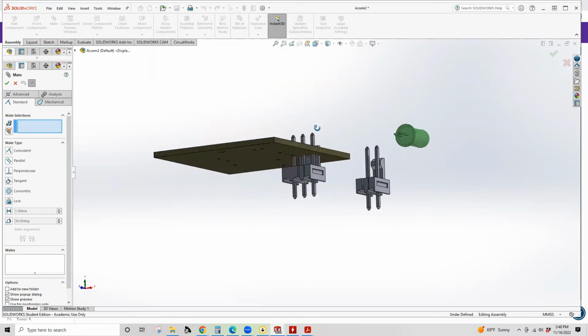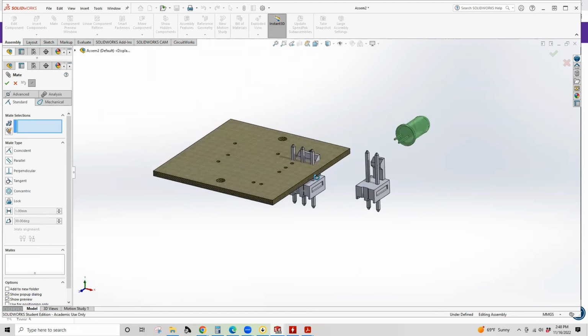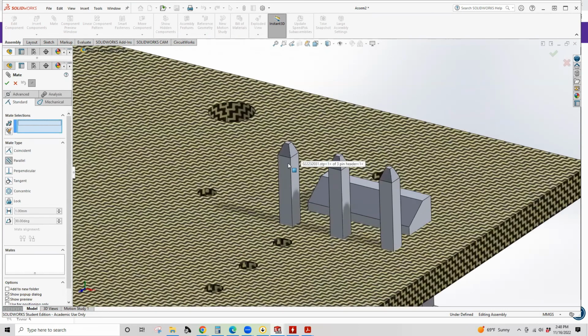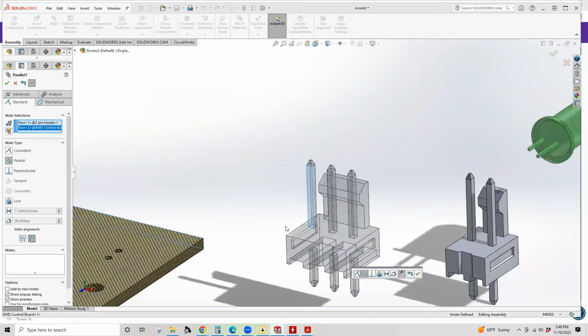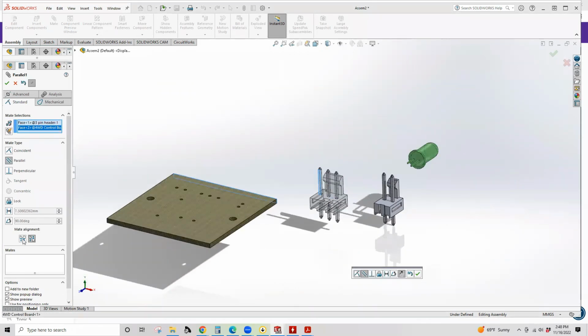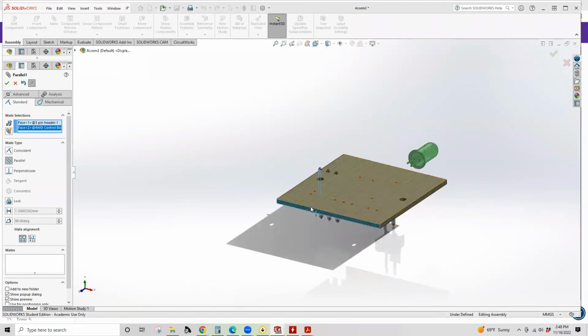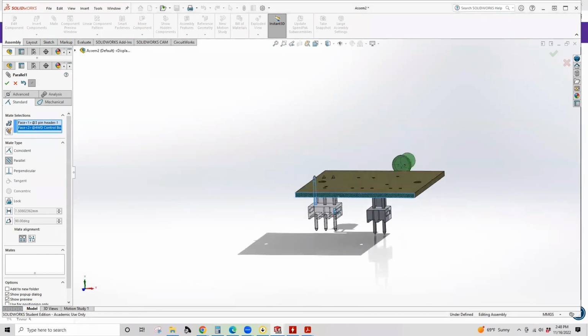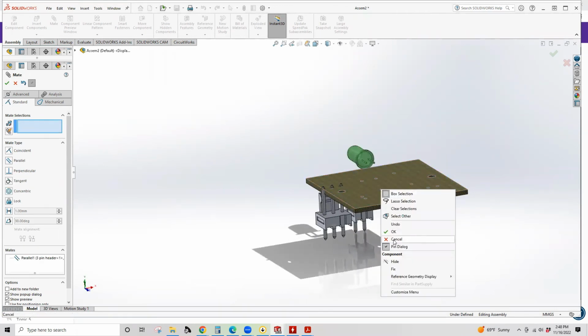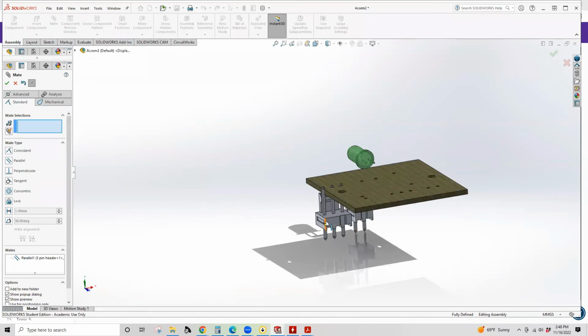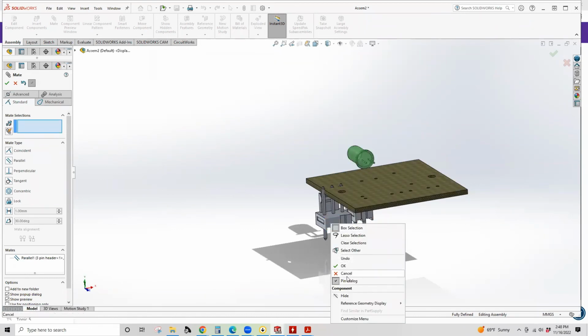Round pins are going to make this interesting. So we make a surface parallel to another surface. Nope, want them co-parallel. Good. Actually, I want to reverse this: fix this, float this.